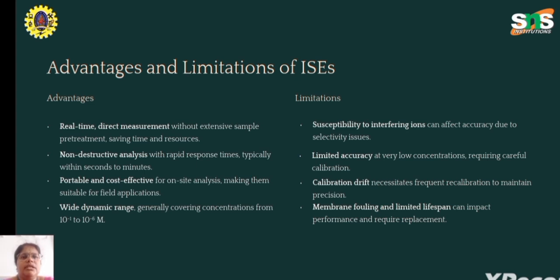What are the advantages and limitations of ISEs? Advantages: real-time, that is, direct measurement without external sample pre-treatment, saving time and resources. Non-destructive analysis with rapid response times, typically within seconds to minutes. Portable and cost-effective for on-site analysis, making them suitable for field application. Wide dynamic range, generally covering concentrations from 10 to the power minus 1 to 10 to the power minus 6 molar. Limitation: susceptibility to interfering ions can affect the accuracy due to selectivity